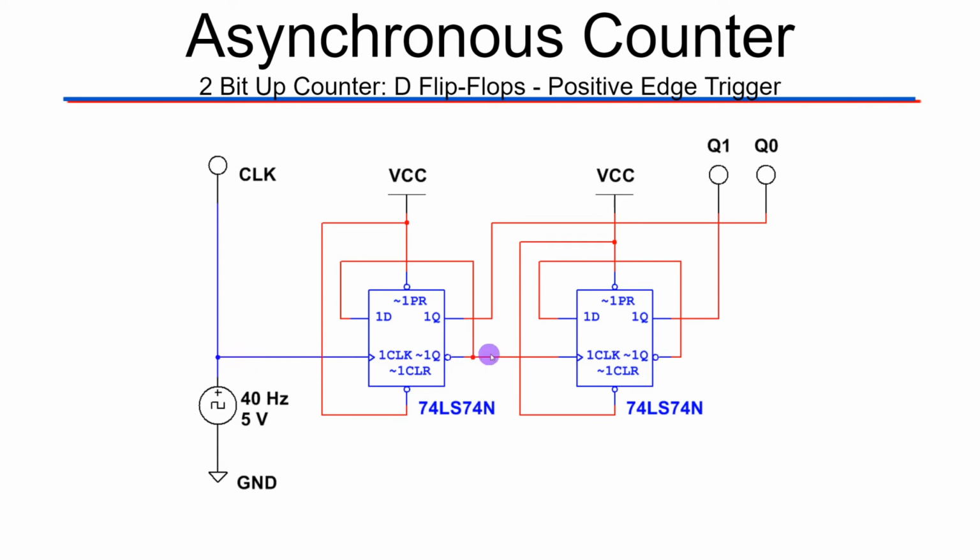All right, this is going to be the same for our build, except that our build is going to be 4 bits instead of 2. So this is one of the more difficult things to realize here, is that this clock signal is really the only thing that is enabling this to change state or save a different state, right? So we don't see a negation here on the clock signal coming. So this is a positive edge D flip-flop.